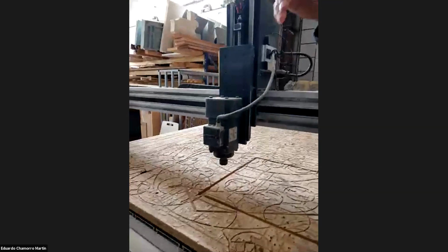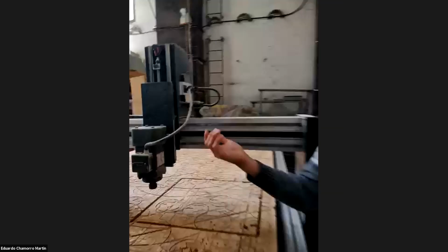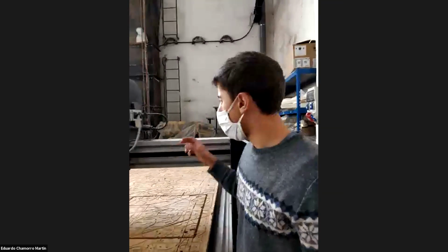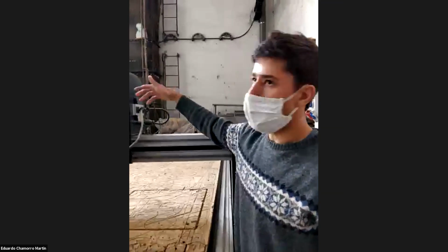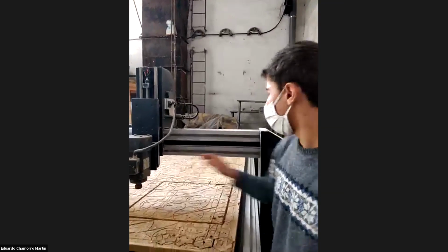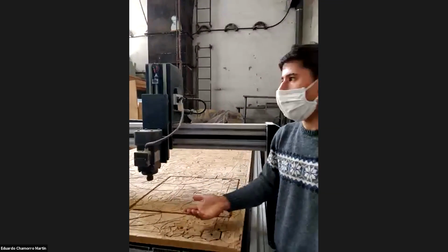One thing that we didn't talk about is that the machine needs to know where it is. We will see later that it's something called homing, so that we find, let's say, the origin of the machine. But at some point, the machine needs to find itself. When you turn on the machine, it doesn't know where it is. I just moved it, and no one told it. Powered off, it doesn't have any memory. How do you do it?